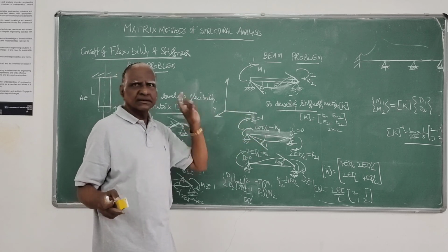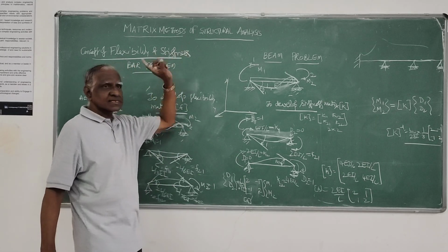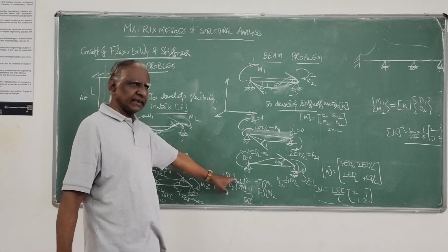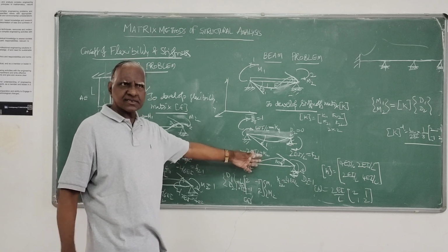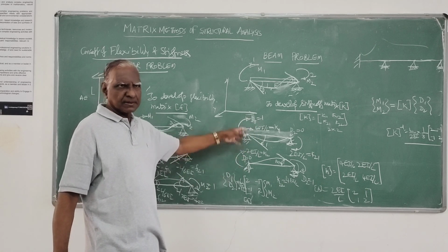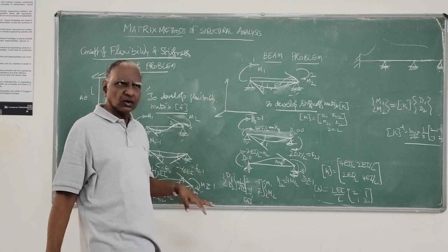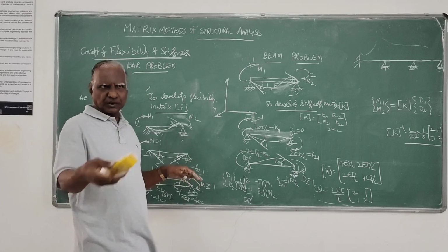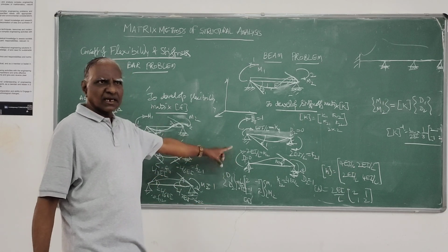The basic concept of stiffness, flexibility, and the methodology involved in our matrix stiffness method of analysis, that also has been explained. That is, you have to generate the stiffness matrix by this procedure. All these fundamental basic concepts you have already developed because of unit translation. That is 12EI by L cube, 6EI by L square, those things are also known. Remembering those fundamental things, you can work any problem. So from next onwards, we will take up examples straight away. You remember all these concepts.